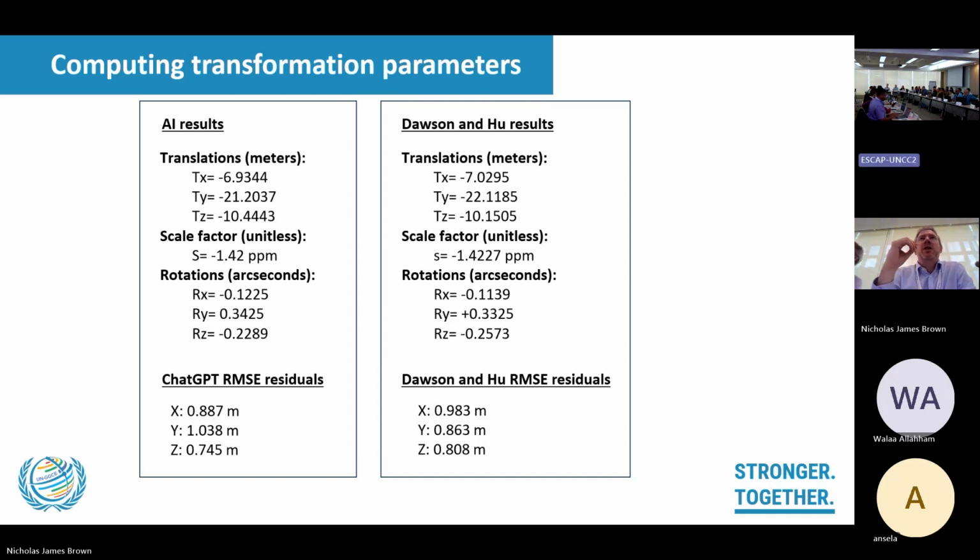So if it's an old one, I'd try and understand the geoid ellipsoid separation of that. Was the local spheroid that was developed done to try and fit Singapore well? Then I think you could use what Richard is suggesting, and I think it would work very well. You could assume that it's 0 or use the ellipsoidal height of the other one, so assume the difference between them is 0. I think that's a fair assumption. That would be worth trying, and then see what residuals you get.